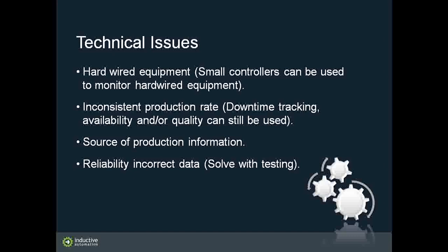It's easy to put in logic and PLCs and configuration on the OEE downtime system, and then find out that it's not getting the counts correctly or detecting a downtime reason correctly. So run through the system and go through a commissioning stage to make sure the data is as accurate as possible.